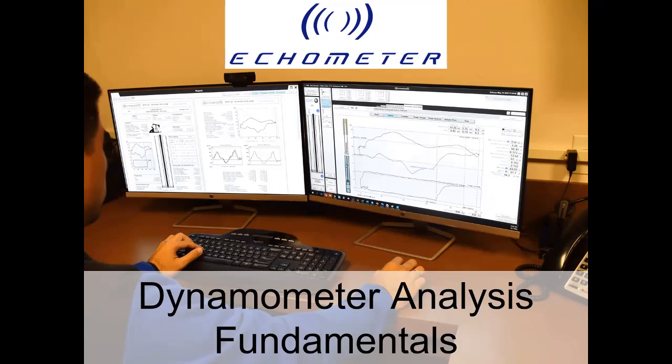So one of the things that we have to focus on when we're analyzing dyno cards is first understanding what a dyno card means and what is that graph, what kind of information is it providing. And basically, a dynamometer card is one of the primary tools that you will have available to analyze a rod pump system performance.